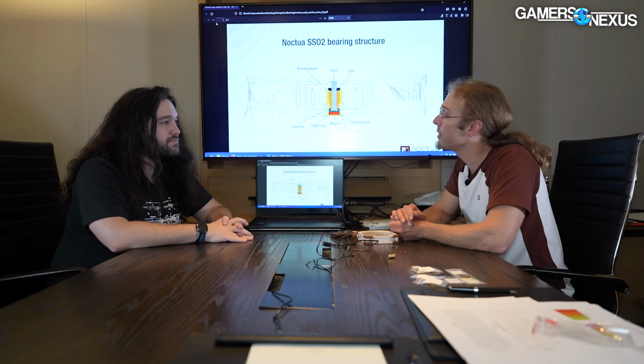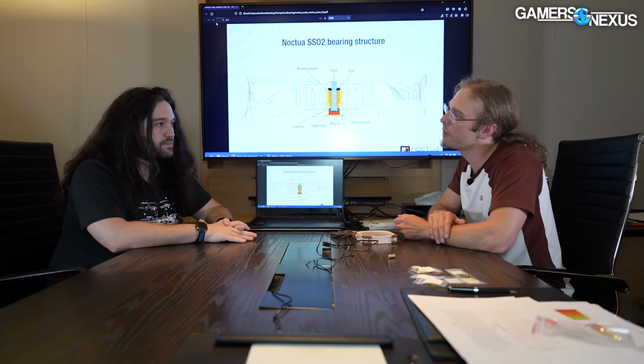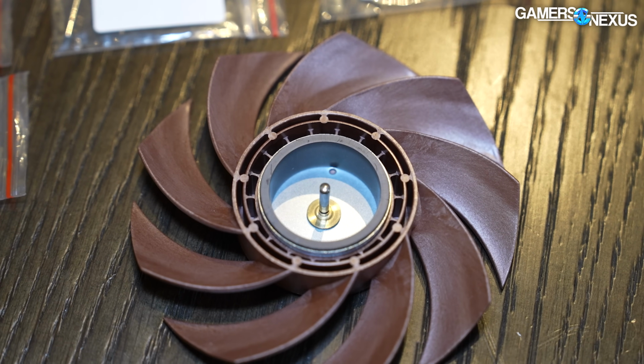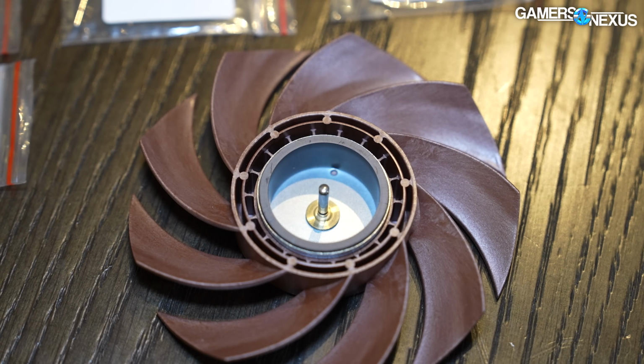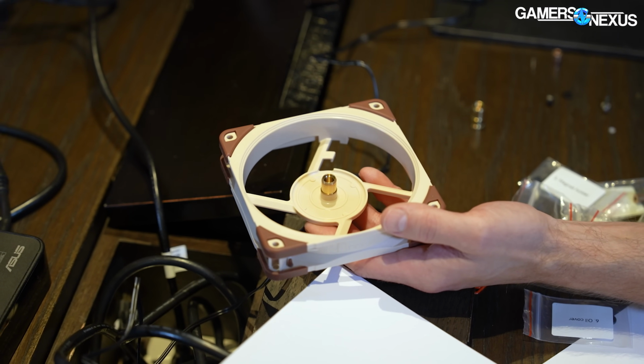For us, the magnet is obviously a vital part because we already talked about those dynamic pressure fields building up when the shaft is rotating. It takes a few fractions of a second, we're talking a few tenths of a second, but still, for those pressure fields to build up, even if you have those FDB herringbone grooves. The beauty of having a magnet inside for extra axis stabilization is that we have that stabilization from the get-go. Okay. And that reduces the initial gyro effect on the fan that actually is quite critical from a wear perspective.